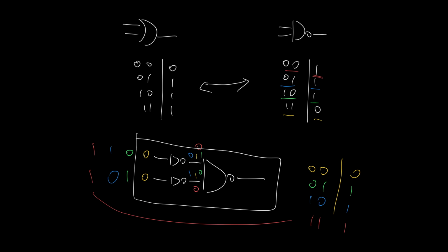These two blocks go into AND gates. To get an AND gate, I just put it through a NAND gate followed by an inverter. And so therefore this goes into a NAND gate followed by an inverter, but an inverter made using a NAND gate looks like that. Same as this, to put this into an AND gate, I put it into a NAND gate and then into an inverter.